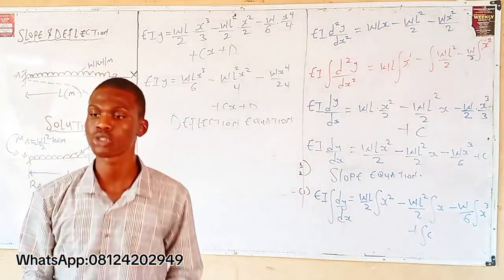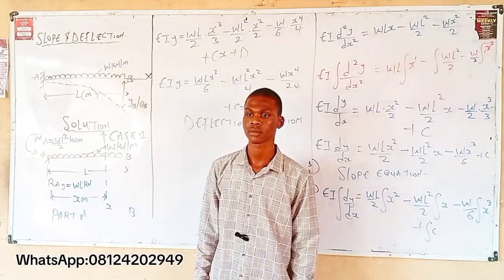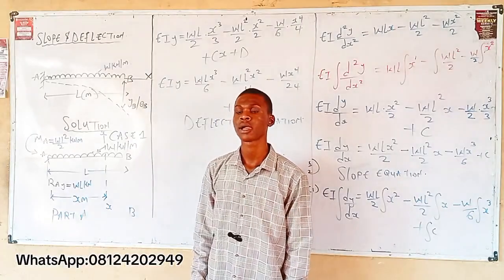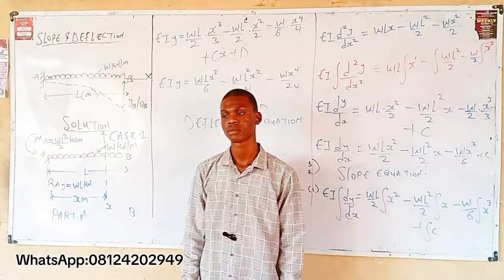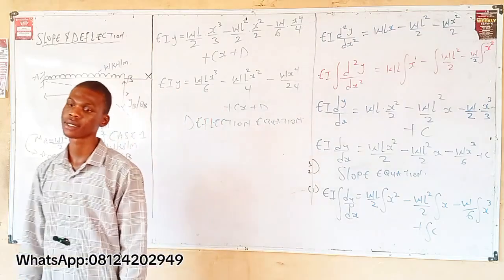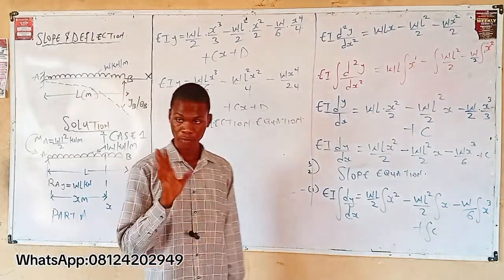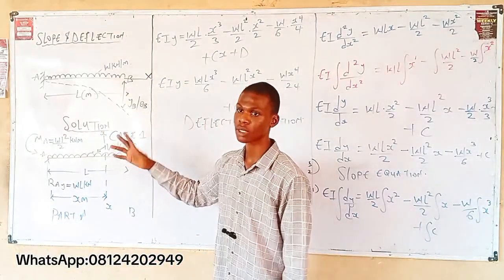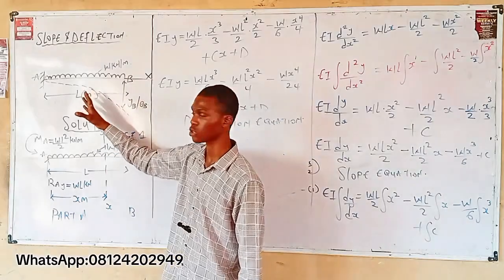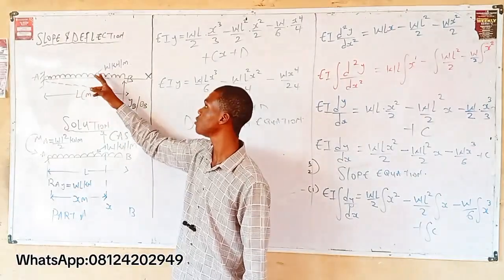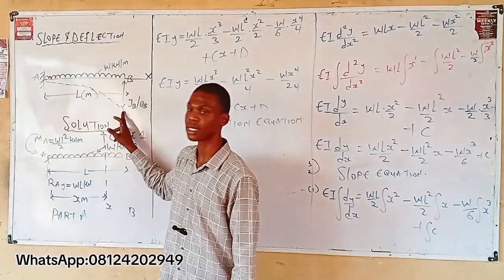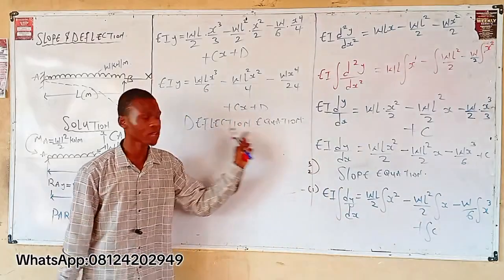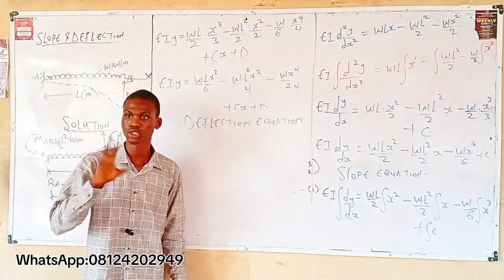So this is your deflection equation. You need to go through all this formula. You can just write down that formula and pick the elements of the question. What it means is, according to the question he asked me now, does that mean that given a similar question under cantilever, whereby you know the value of the UDL and the total length, can you just write out this slope equation and this deflection equation, and substitute?